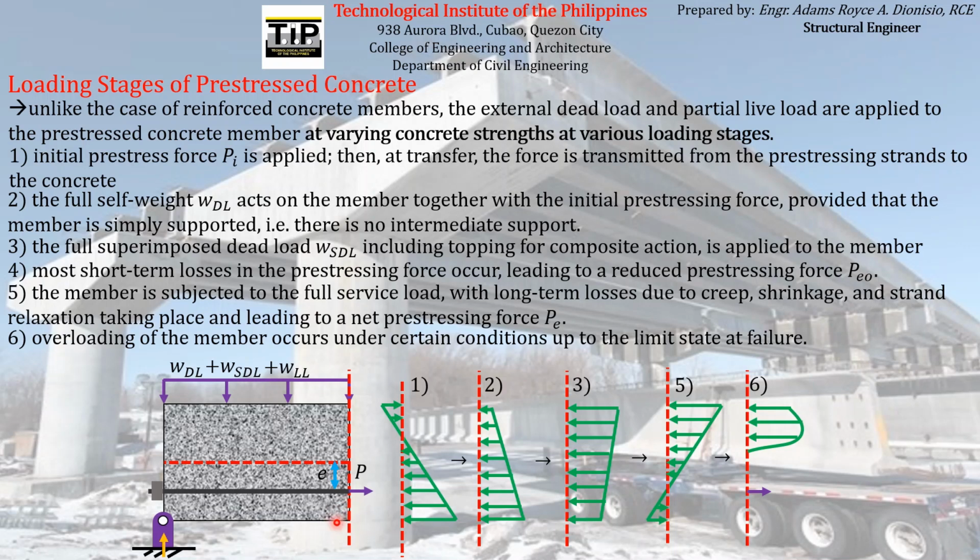The cracks will now form on the bottom part of the concrete element, and because of that cracking, failure of the concrete will occur. Those small cracks can easily propagate to the upper portion of the concrete.